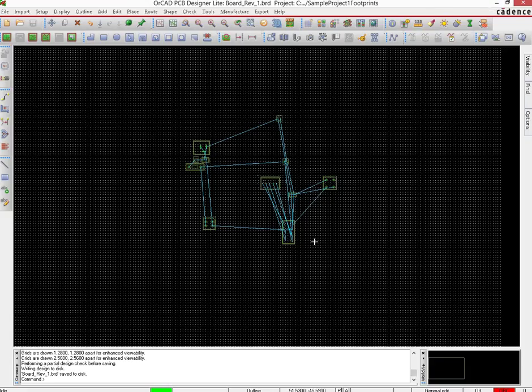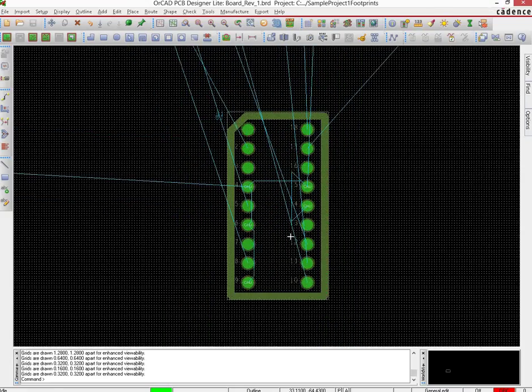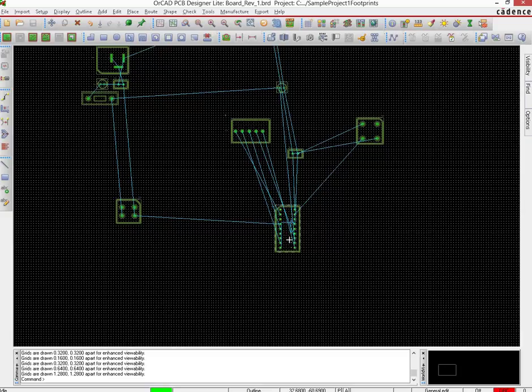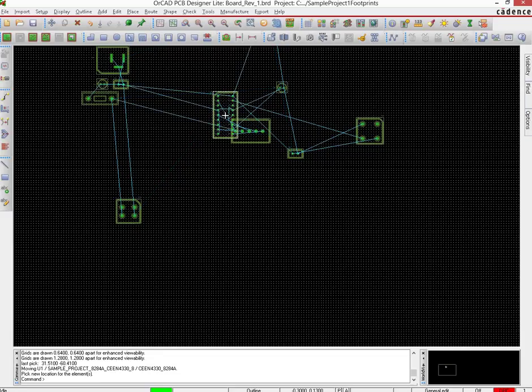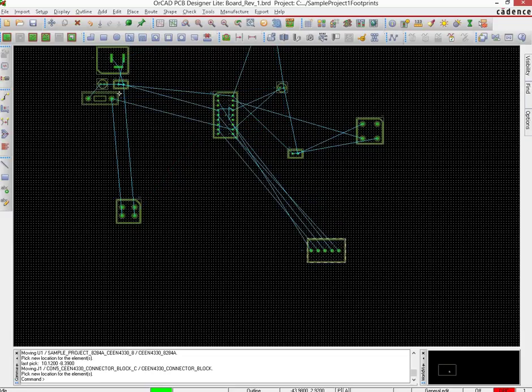Okay. Now the clock IC by itself is this one. So let us place it somewhere which is central to the board, for example, let's say. And then let us take this out for now. Then what we have is this is the switch 2. So the switch is related with our reset circuitry. So let us do that. Let us have the switch somewhere here.